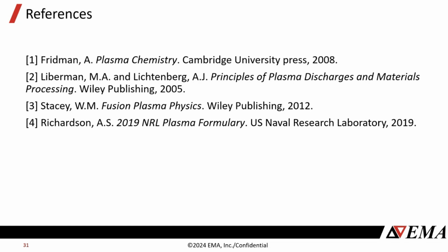Gotcha. Next question. How many reactions can I expect to have in a discharge model? Yeah, so that largely comes down to what kind of gas you're modeling. If you're going for a more simple gas like H2 or N2, these simple diatomic gases, you could have like 40 to 70 reactions in your model.